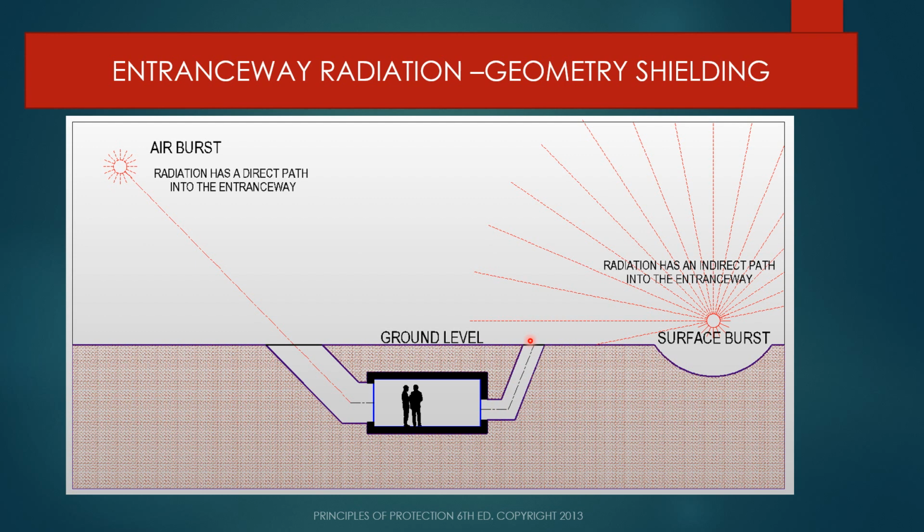This is where the radiation comes in, and that's the shielding that we do. You can put a barrier shielding in there, and you can use the tables from the overhead radiation shielding, and you can reduce that. But if you use steel to reduce it by half, you're going to have to put 1.2 inch thick steel. It's usually not economical to put that heavy a plate of steel in these entranceways, and then you have to put it on hinges. It's pretty expensive.